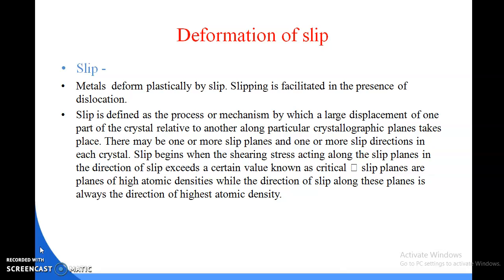Slip begins when the shearing stress acting along the slip plane in the direction of slip exceeds a certain value known as the critical resolved shear stress. The slip planes are planes of high atomic density, while the direction of slip along these planes is always the direction of highest atomic density.